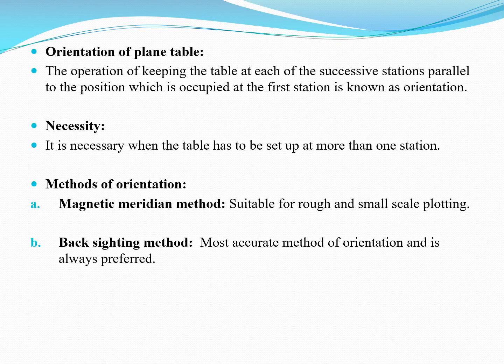Initially, the plane table is set over station P. After that, all the arrangements are done as per the setting of plane table, that is, centering and leveling should be done.